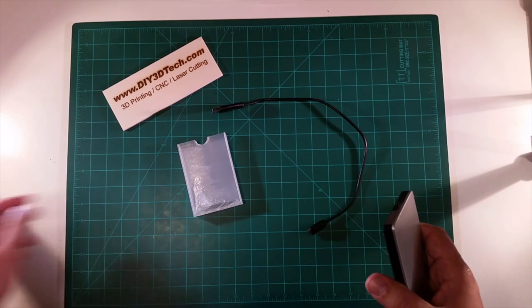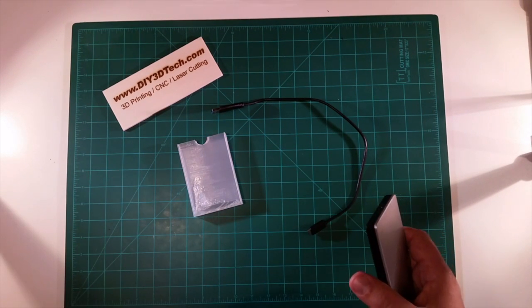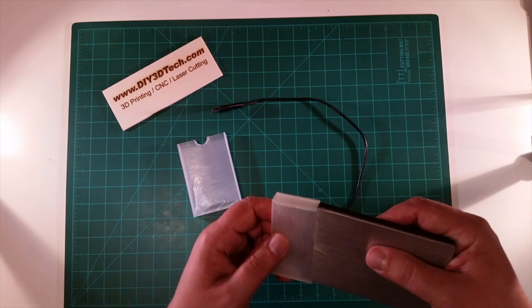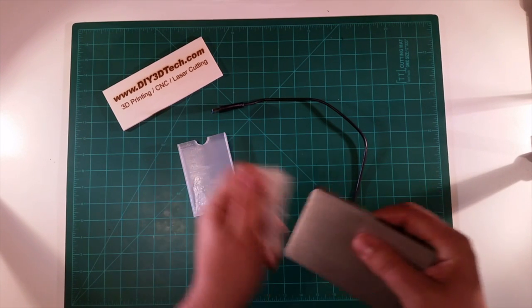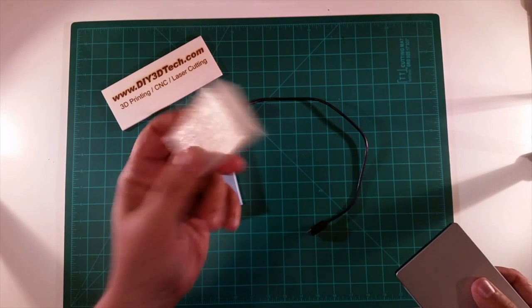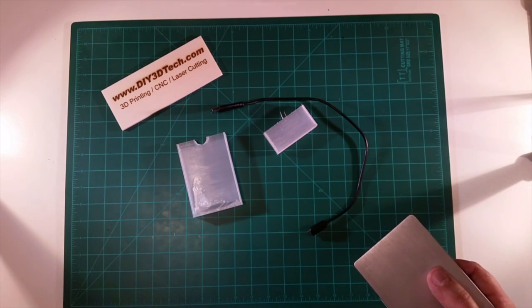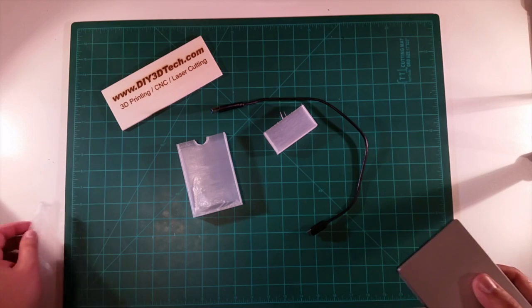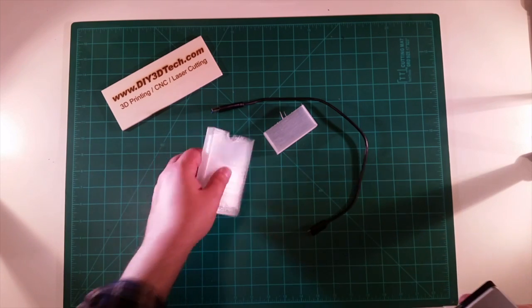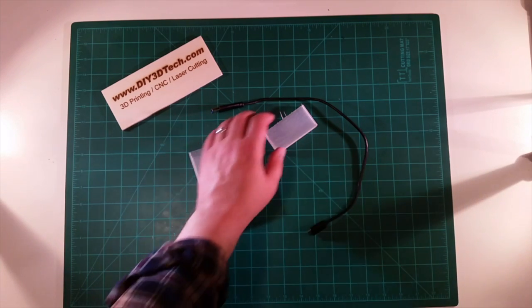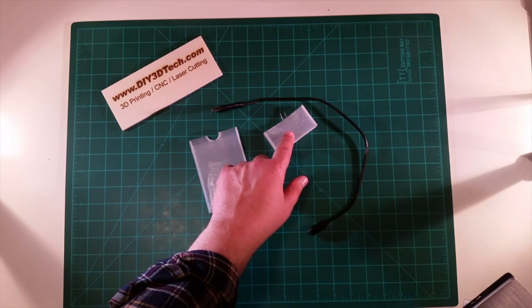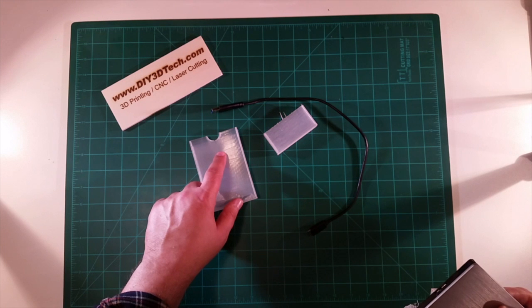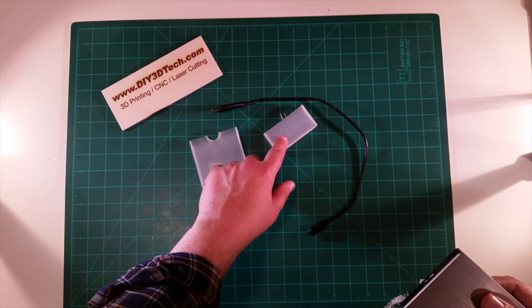So I have given a shot at reprinting it in a couple different ways. For example, in this version, I tried changing the wall thickness. You know, this one failed. Again, I tried. Now, one of the things to mention is when I printed both of these, this is a 1.5 millimeter wall thickness. This is 1 millimeter wall thickness. The 1.5 did far better than the 1.